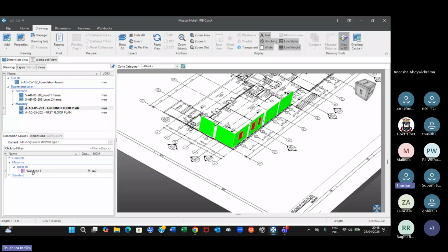So same concept, right? Normally when we measure a particular project, the first thing we do is basically counting the windows, but only counting is not enough. That is only for the window section, door section, but you need to do the proper deductions, right? First, when you measure the blockwork, and secondly, when you measure the finishes, wall finishes especially. Right. So you need to understand the sequence. You need to understand the relationship.